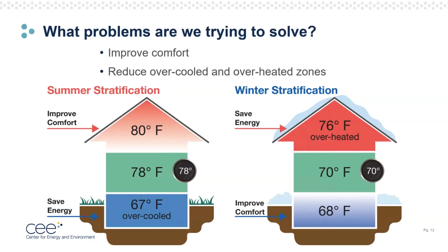This occurs because the single zone air distribution system has a fixed amount of air that's provided to each section of the house. Sometimes the amount of air to each branch wasn't really set properly to begin with, and then in addition, the fraction of supply air needed in each part of the house can change throughout the day. For example, you could have a portion of the house with more southern windows where the cooling load may be greater and heating load reduced on sunny days. In addition, on colder days, the thermal stack effect will increase cold air infiltration in the lower level of the house and have little or no infiltration in the upper level. Finally, as ground temperatures change through the seasons, the basement heating and cooling load changes.